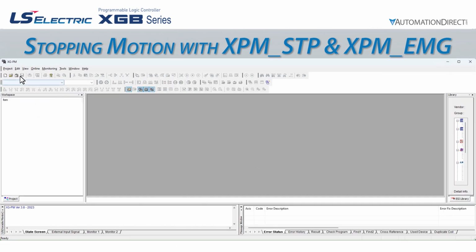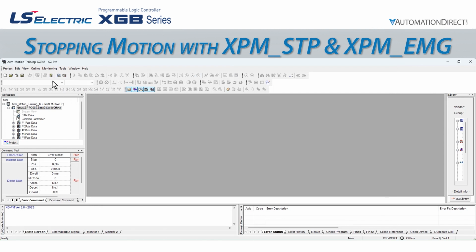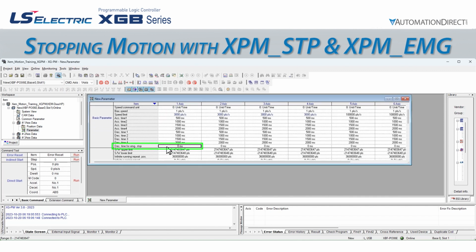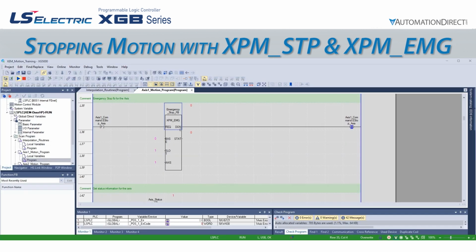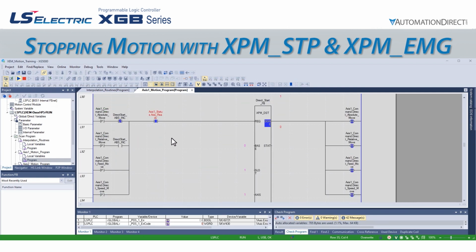Once XGPM is open, we can open XEM Motion Training XGPM and go online with the motion controller. If we go to the axis parameters, we can see that the decel time for emergency stop is set to 0 milliseconds. Let's go back to XG5000 and set up our direct start. We can scroll down to line 90 to see our direct start function block. We cover the direct start function block in another help topic, so please refer to it for further details.